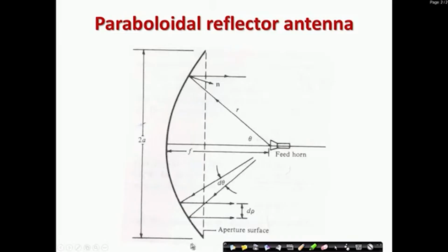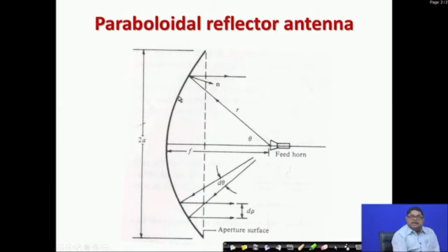But people can also say that I can find out at this paraboloid reflector what is the current, because this is not an aperture problem, this is a real paraboloid conducting surface. So, I can find the conduction current here, and from that also I can find the field. Both methods are there. This is called the induced current method, by which wire antennas are analyzed.